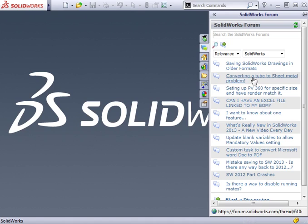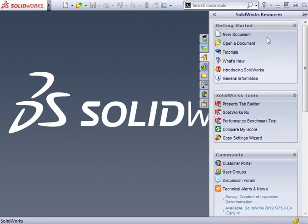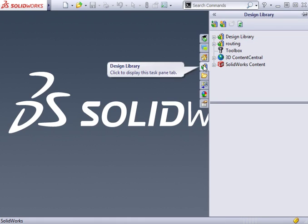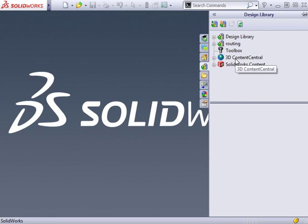In the upper right-hand corner of the SolidWorks interface is the Search box, which you can use to find your SolidWorks files, or search the Help file, community forums, or knowledge base. The Search window also allows you to find and run a command simply by typing the name here. So if you're having trouble finding a particular feature or command in the drop-down list, you can simply search for it here under Commands and access it right away.